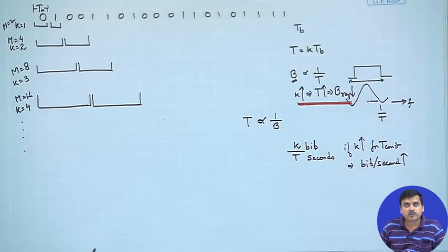So, overall, what we could summarize is that by increasing the modulation order, you are packing more bits per symbol, thereby using your channel or system more effectively than by sending 1 bit per symbol. Now, here you can clearly distinguish the difference between an analog communication system and a digital communication system. In this particular system, if things permit, which we will see with reasons later on, we could practically make M very large.